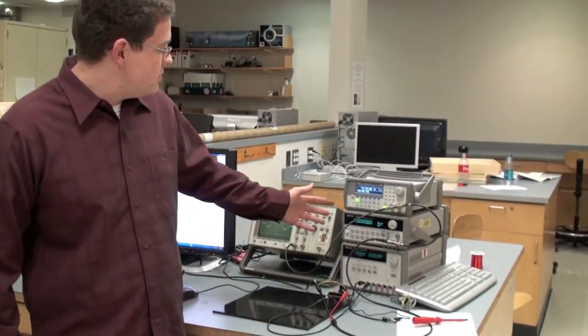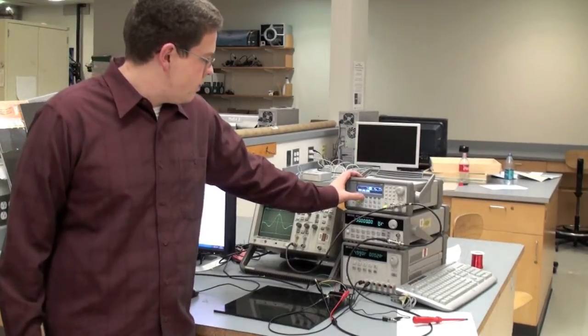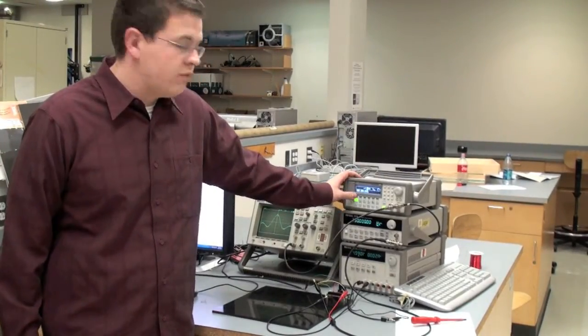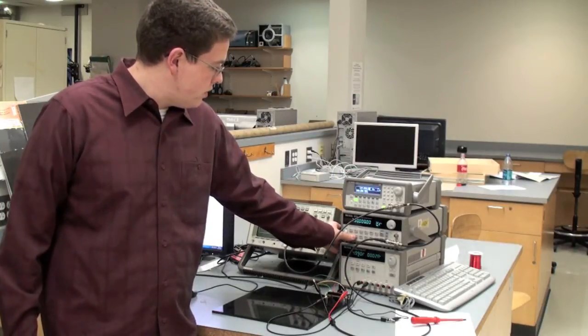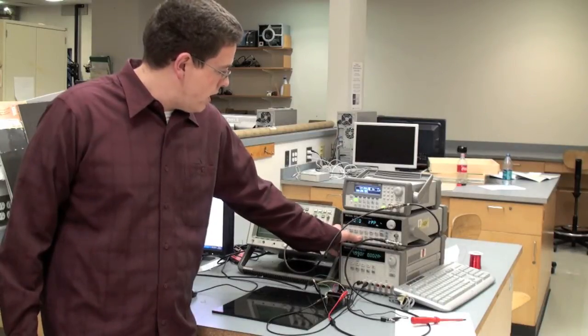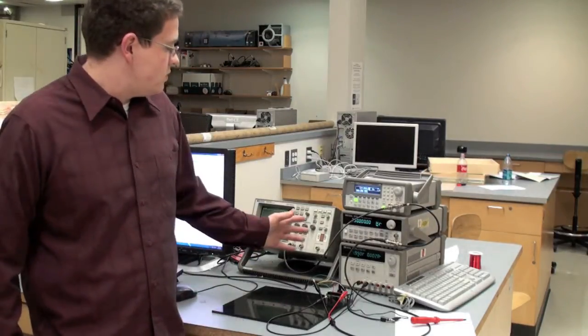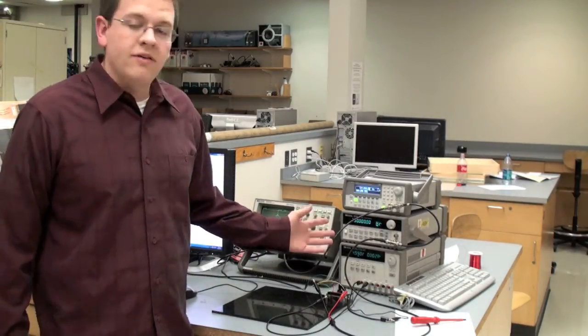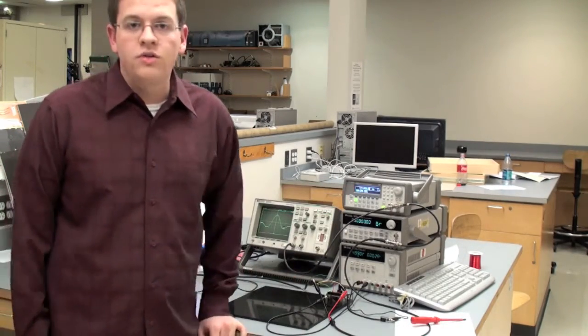We're inputting two signals. We have one here at 121 hertz, 1.6 volts, and a 1.1 volt offset. And the second one has 230 hertz frequency, 1.2 volt, and a 1.1 volt offset. And they're both sinusoidal waves, and the point of the two different waves is to show that our FFT will show two spikes, one at 121 hertz and one at 230 hertz.